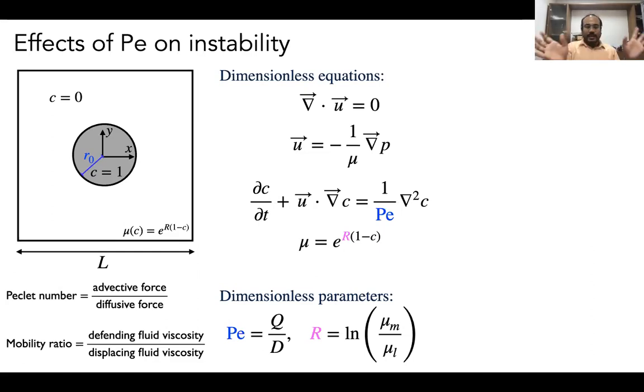So we first said, consider that there is no reaction, or consider the scenario that the reactant A and the product C have the same viscosity, which is less than the viscosity of B. Then by some scaling argument, we can write that the concentration of the reactant B is 0 outside, and the concentration of A plus C is 0 outside in this white region, and the other one is 1. With this scaling argument, we eventually get a dimensionless equation that reads like the following.